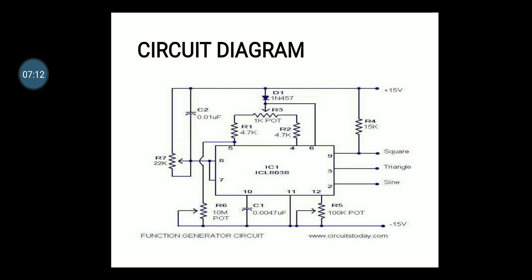The voltage across the capacitor is applied to the Schmitt trigger. The Schmitt trigger is similar to that of an IC555 timer. The upper comparator has a voltage of 2 by 3 VCC and the lower comparator has 1 by 3 VCC. Transistor Q7 acts as a switch. When the output of the flip-flop is high, Q7 saturates and pulls the base of Q5 and Q6 low, thus shutting off the current sink. As a result, the capacitor starts charging at a rate set by the current IA.